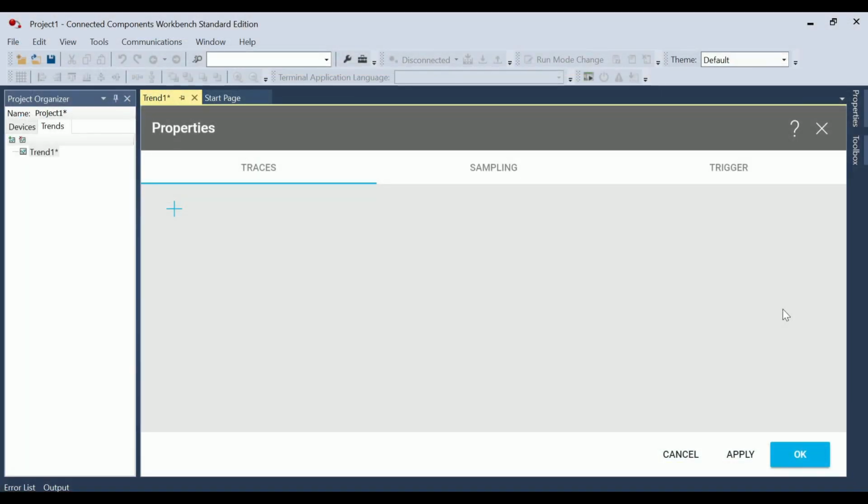Now, careful though, it's also helping us to run tuning. If we wish to tune our variator for position, for a larger torque, or even for more velocity, then we can start watching our variables for our graph, and little by little adjust our gains manually. This way, it's going to be set up for more advanced and more calculated numbers. So basically, this is the trends part, or for our graphs.